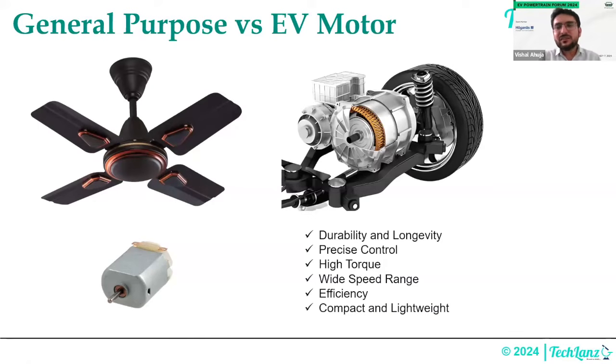You also don't want these motors to be as bulky as your pump motors, such as the three-phase pump motor you might be using at home. You want them to be compact and lightweight, which Sajal also covered, that is why these motors are different. And then you don't want your vehicle to make a huge amount of noise. When pumps are running, they make a huge amount of noise. You don't want that to happen on an EV motor. So these are the requirements on the EV motor that make it different in terms of application.